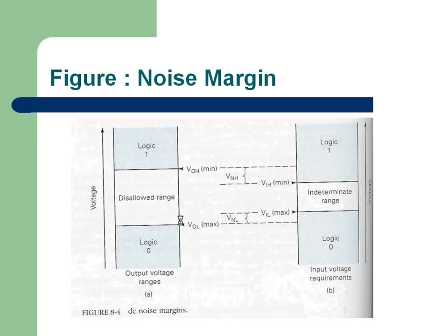Yeah, this one. So this is the driving logic output, and this is the other logic input. When the driving logic output is low, it is going to give this value. The reading logic will have a little bit higher threshold, so this will be the maximum, obviously. In this case, we have to consider VOL maximum only. Usually, when it comes to CMOS, VOL and VOH will be fixed values.